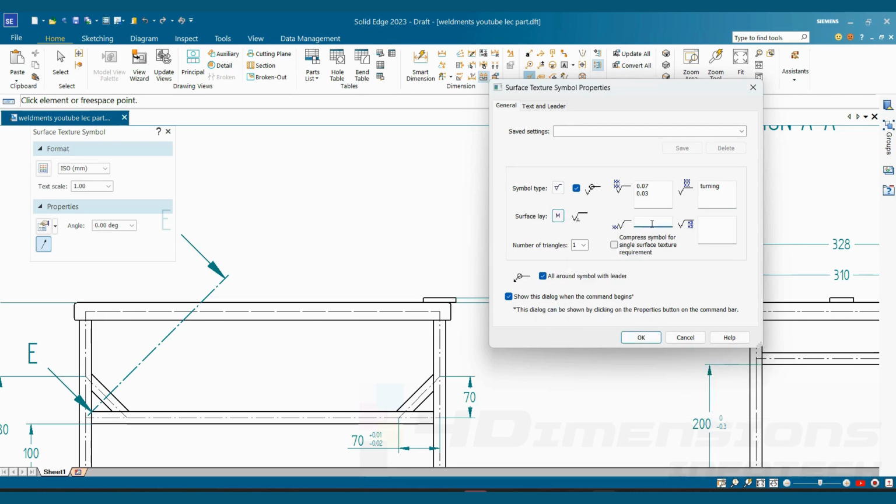Next is the allowance. Now this allowance is compulsory. Only if the extra material or allowance is kept is machining possible. So the machining roughness values we required were 70 microns to 30 microns. So for that I am going to keep the allowance here as 0.2, meaning 200 microns. So here the allowance is 200 microns. By machining processes, we need to bring the surface roughness between 70 microns to 30 microns.